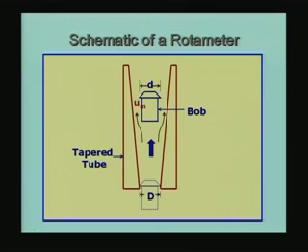The corresponding division on the outside will give you the height above the datum. So that gives you the y. So you actually measure only the y, the scale reading on the periphery of the taper tube, and from that you multiply by a constant capital C, which is called the gauge constant for the rotameter,